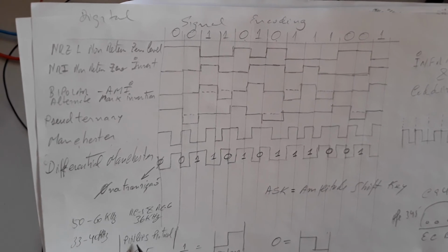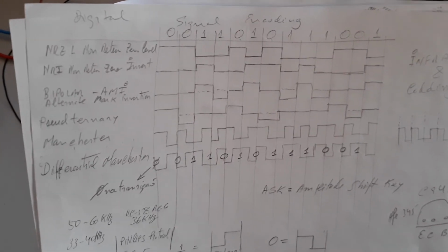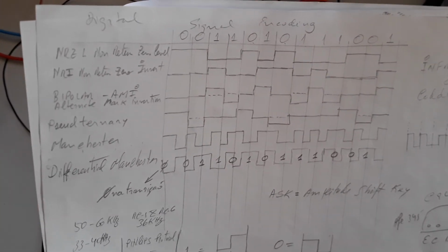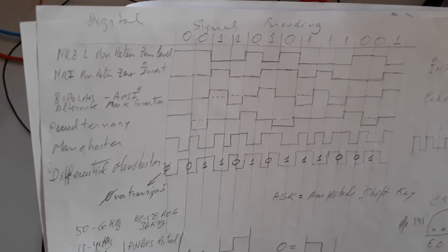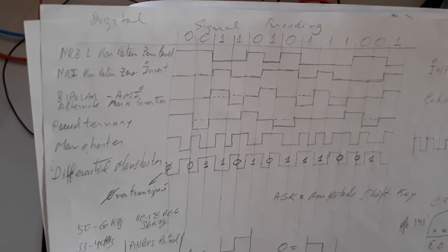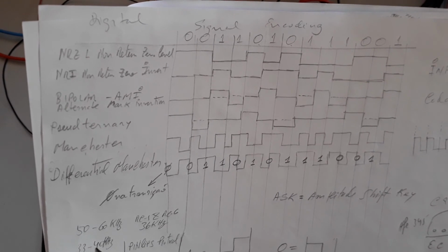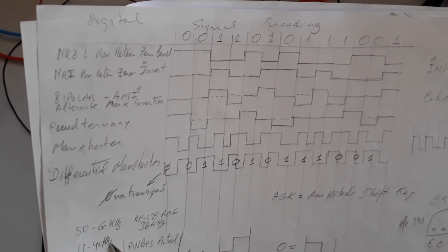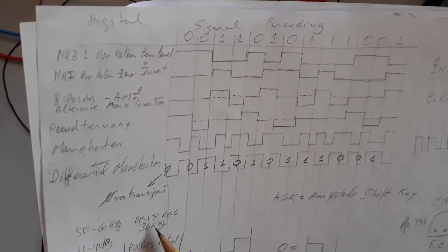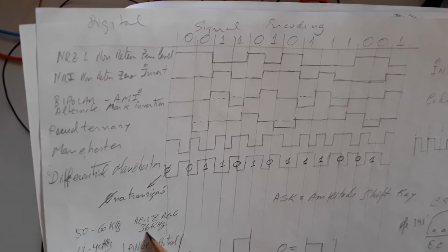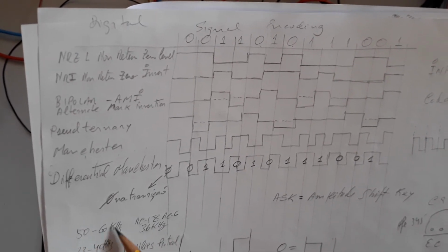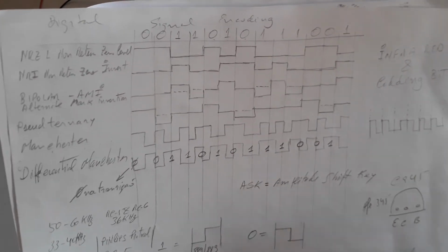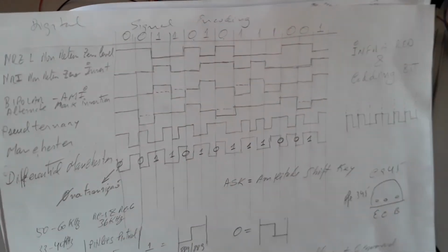You need to take care with the Philips protocol, RC5 or NEC, and the normal frequency range, depending on the receiver and the emitter, 33 or 40 kilohertz, or 36 kilohertz, or 50 or 60 kilohertz, okay, depending on the protocol you use and your hardware you need to implement this, okay.